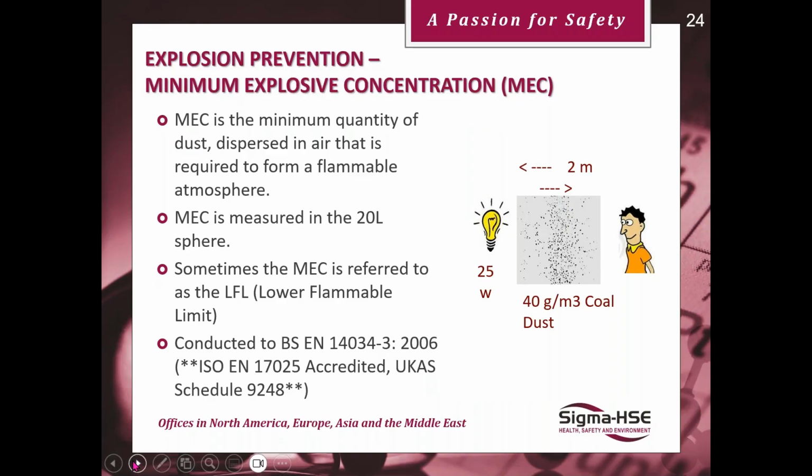Conducted to BS EN 14034, and it's tested in our laboratories. And some bright spark, and I don't know who it is, comes up with a suggestion that at 40 grams per cubic meter of coal dust, you can't see, or you're struggling to see, a 25-watt light bulb from 2 meters. So it's a pretty dense dust cloud to support combustion.